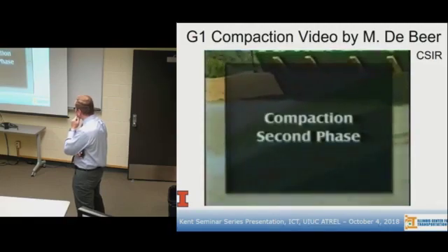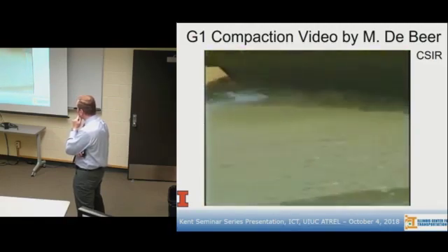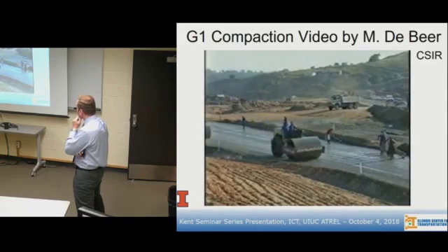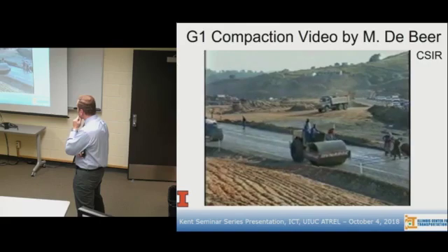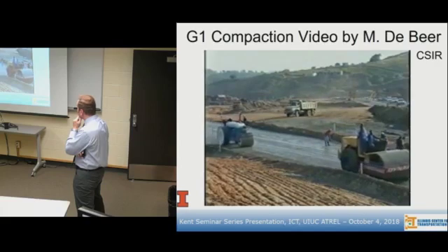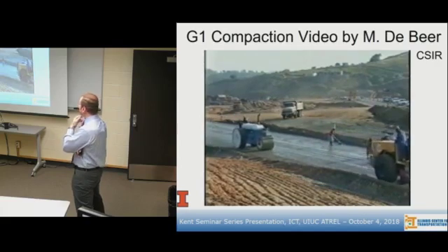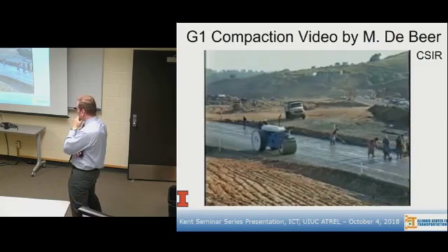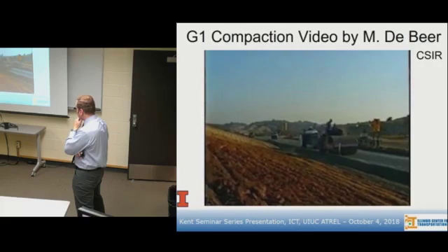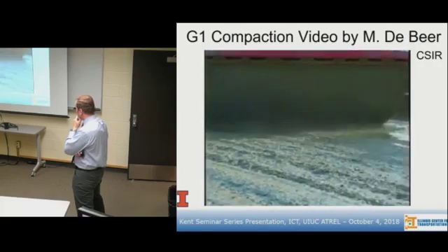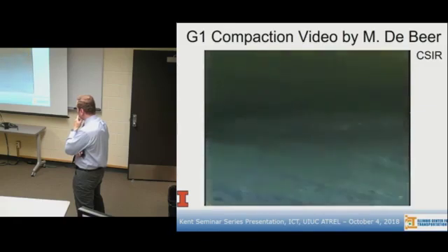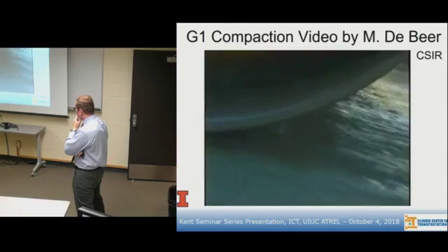The second phase of the compaction process can now begin. The particle interlocking phase involves consolidating the material under saturated conditions by expelling or slushing out the excess fine material from the matrix, allowing the larger particles to interlock into a super dense matrix. The purpose of this phase of compaction is to knit the different sized aggregate particles into a super-dense interlocked mass by consolidating the layer and slushing the excess fines out of the matrix.